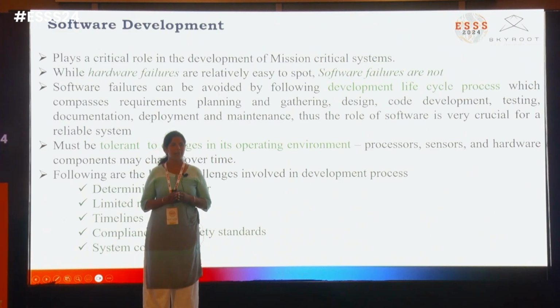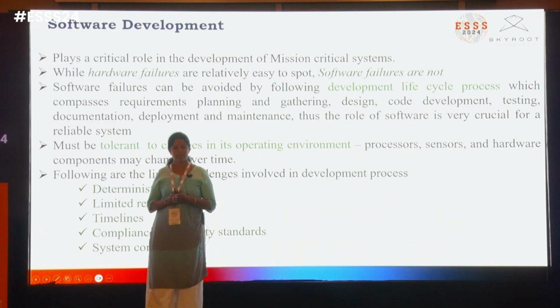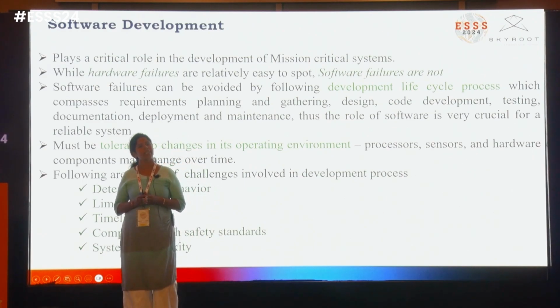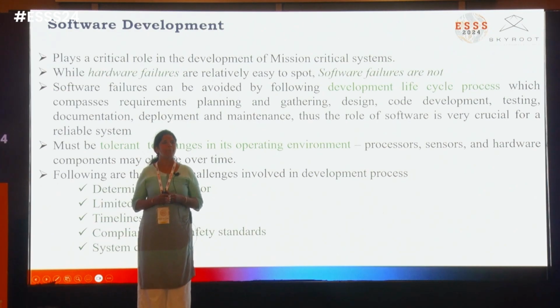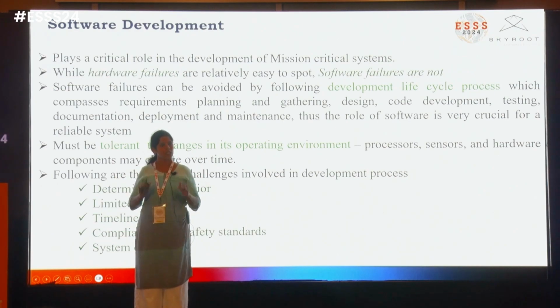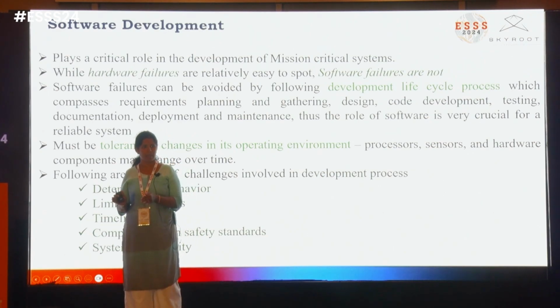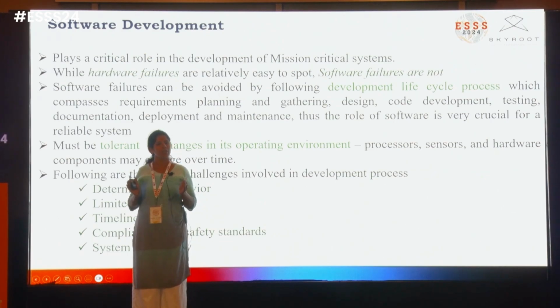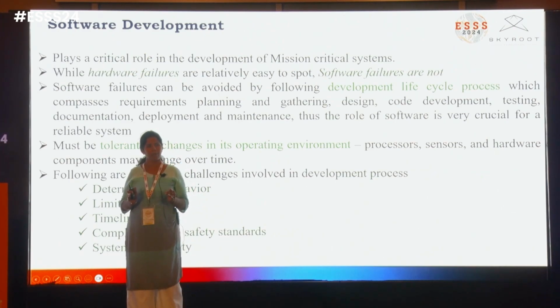That is why it becomes very challenging to get the deterministic behavior, and achieving this deterministic behavior in limited resources. Example, if we have 1 MB of RAM, your entire application is supposed to fit into that 1 MB of RAM. You can't exceed the 1 MB of RAM. So how do you make sure that your application fits into 1 MB of RAM?